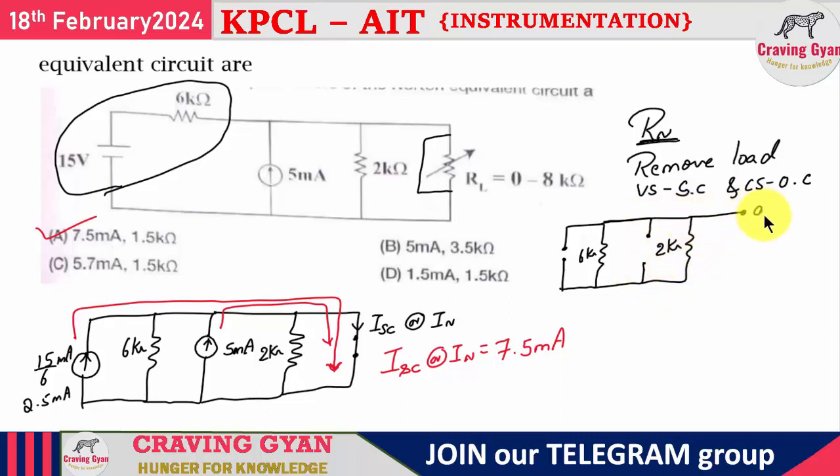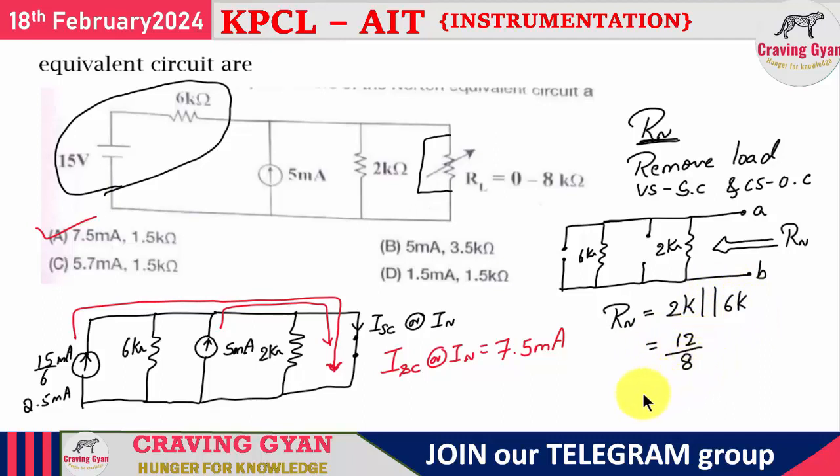Now this is the terminal. I am going to take it as A and B. Now looking at this terminal, what is the resistance that is offered, referred to as Norton resistance, or even Thevenin's resistance, is also the same. Now the Norton resistance means you will be having the two resistors that are connected in parallel, 2 kilo and 6 kilo. What is the equivalent of it? 2 into 6 divided by 2 plus 6. So the Norton equivalent resistance is 3 by 2 or 1.5 kilo ohms. 1.5 kilo ohms, right? Option A is going to follow.